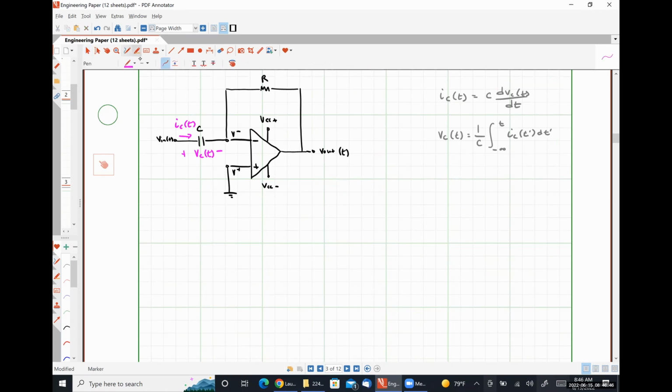All right, so let's apply our normal process to the circuit. Applying op-amp rule number 1, we observe no current can flow into or out of our input terminals. And by inspection, we see that our voltage V plus is 0 volts. Applying op-amp rule number 2, we can observe that V minus must be equal to V plus, so this is also 0 volts. And now we're going to apply Kirchhoff's current law at our inverting input node.